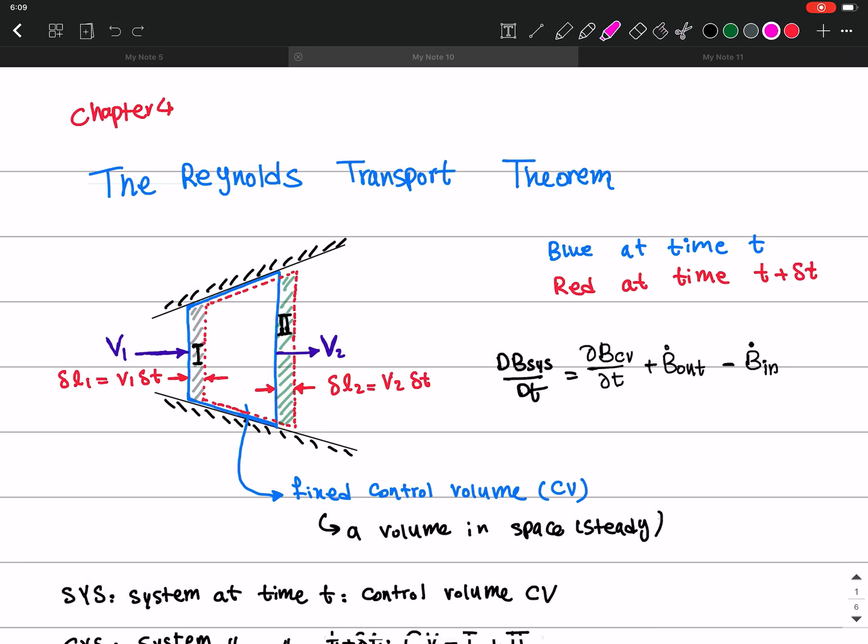Okay. And very intuitively, you can understand what this means, right? So this is just from this perspective, when you look at the flow in this coordinate system with a fixed control volume, you can write this equation, which is going to be the local change of any fluid parameter plus the change in the outflow minus the change of the inflow that is coming to that control volume.